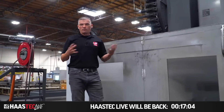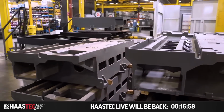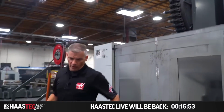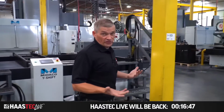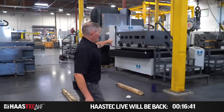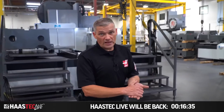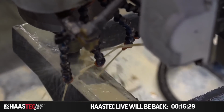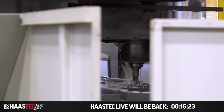So we've kind of run 2 different things here. Medium-sized lathe bases, small lathe bases, and then on some of the other cells we run medium and small VMC castings. So let's go walk down this aisleway here. So we've been running these VS3 cells for easily more than a decade here. But more recently, we've teamed those up with these Midaco pallet changers. And it's the same idea as we see on even the FMS systems and any of the EC400s. You're carrying multiple parts so that you can keep the spindle turning the entire time. You've got one part staged, one part being machined, so you keep that spindle turning.